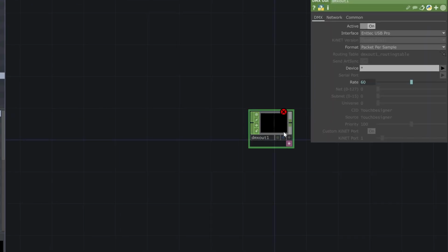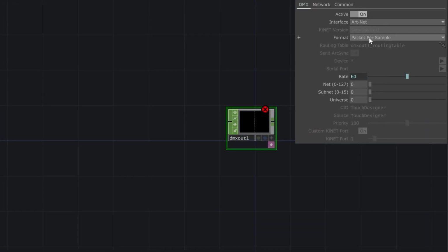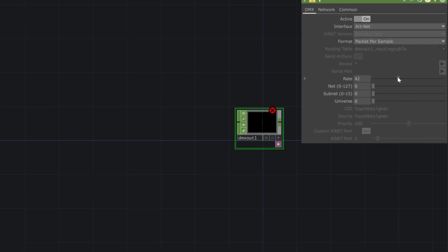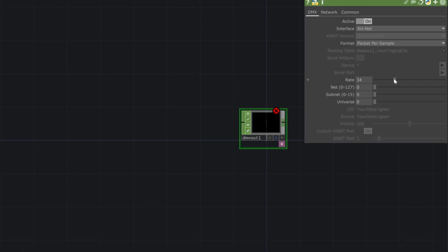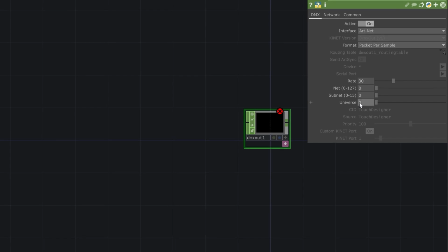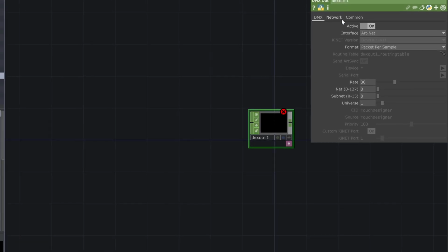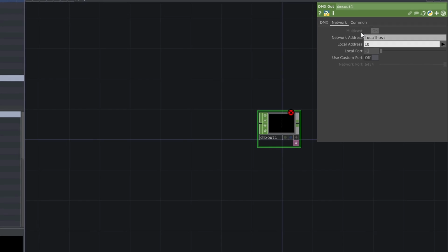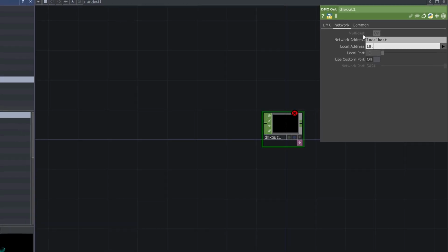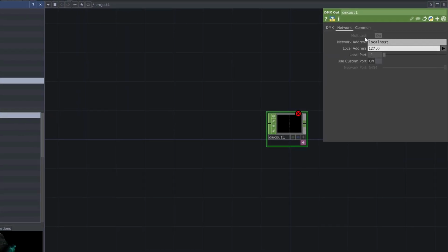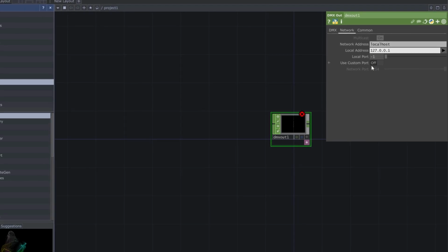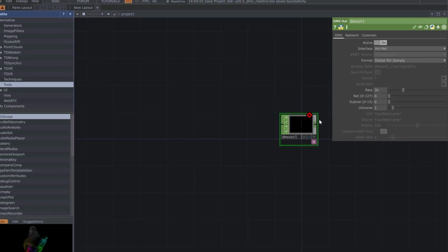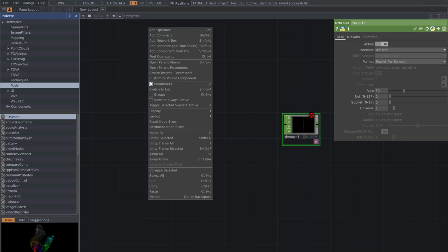So here's where I'm going to grab myself a DMX Out CHOP, and we're going to set it to the ArtNet protocol, and we're going to get the rate down to 30, which was a recommendation by someone else. I still don't know what the official setting should be. We're going to set it up to use Universe 1. Then we're going to assign the localhost to the network and use the same ID that we had in UE5 here. So basically your home IP, 127.0.0.1.